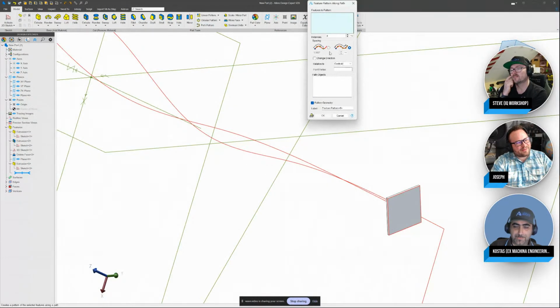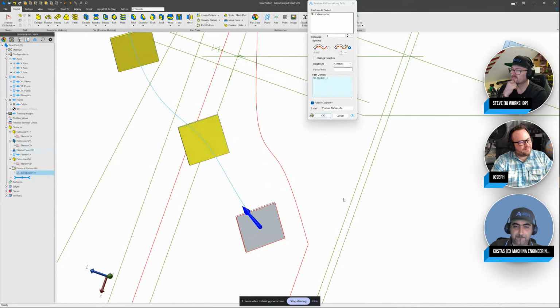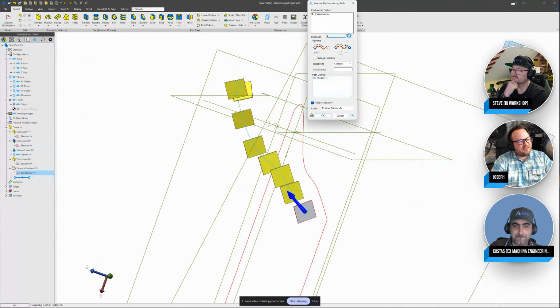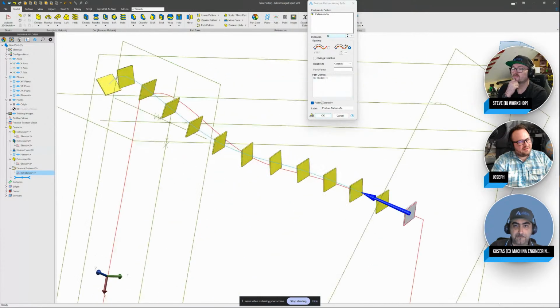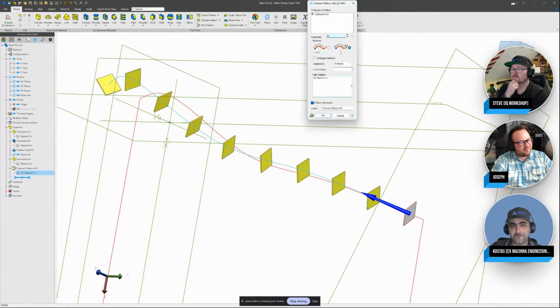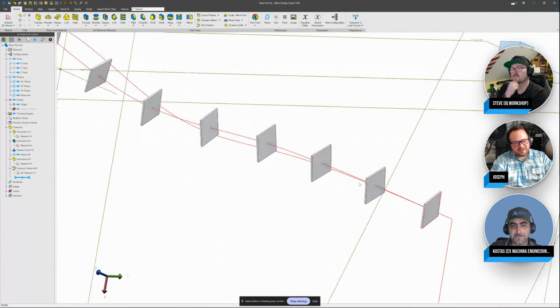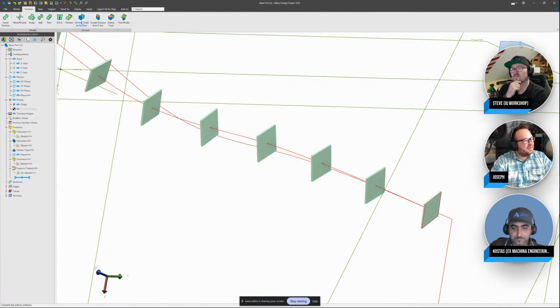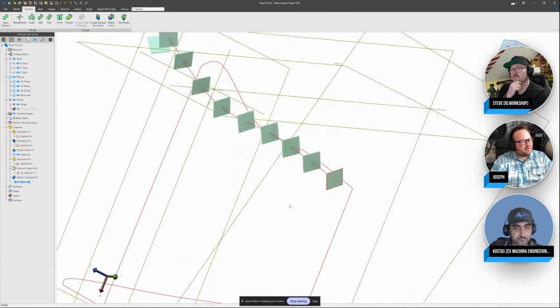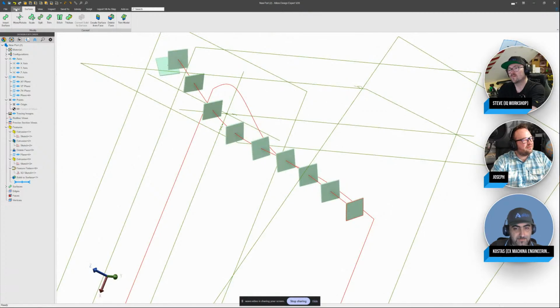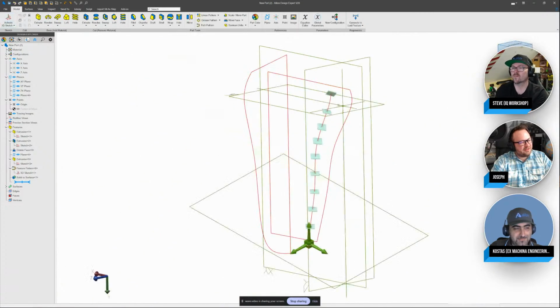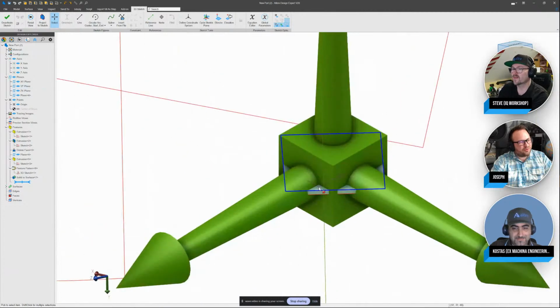I'm going to make a path pattern. We're going to pattern this extrude down this path. And just like that. Maybe I'm going to be a little bit smaller there. So we can tighten it up if we want a sharper angle, or loosen it up if we want a shallower twist angle. And now I can simply run to my surfaces and say convert to surface. All right, this is where the magic begins, although I hope it won't be too tedious for the live. I'm going to pick a corner here.